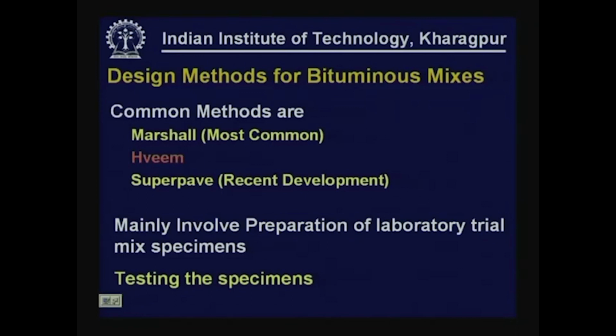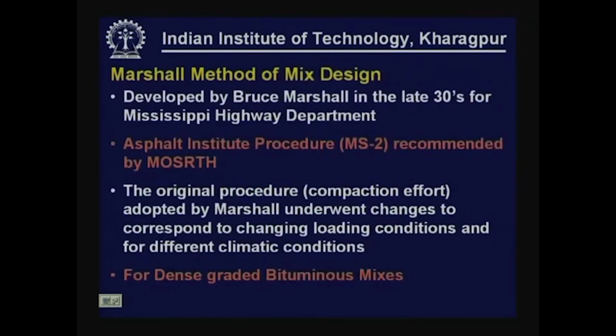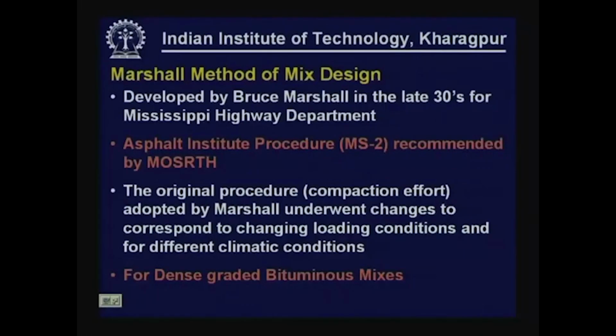All these mix designs mainly involve preparation of laboratory trial mix specimens. That means, a number of specimens would be prepared with various combinations of aggregates and binders, and all these specimens will be tested, and then on the basis of the results that we obtain on these trial mixes, optimum combination of binder and aggregates will be selected. Marshall method of mix design was developed by a gentleman named Bruce Marshall, in the late 30s for the Mississippi Highway Department in the United States.